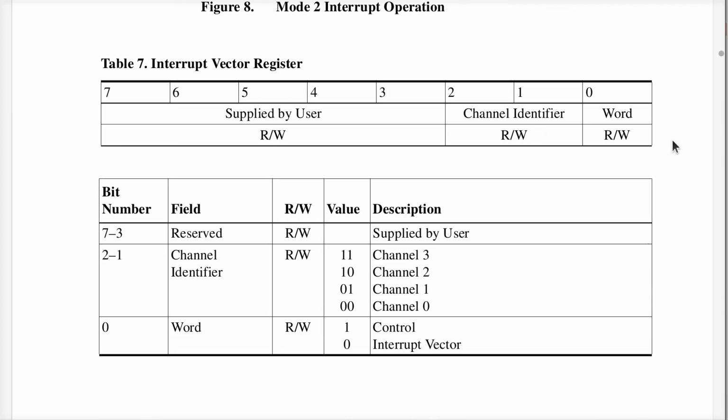Okay, so when I store a 0 in the control word, I'm writing the vector value. Notice that I can set these bits here, 3, 4, 5, 6, and 7. I cannot alter these 3 bits over here. Now, once again, our favorite art department labels these as both readable and writable. I can assure you these are not writable. This is another crappy drawing.